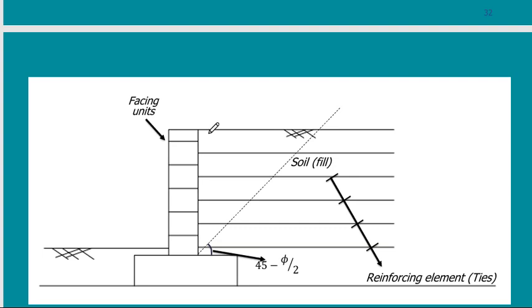I will find that all of this portion will fall down like this. So actually, when I put my wall, I am preventing this portion from falling. How to prevent it? I need to add, after this line, these lines that are preventing my soil from falling. So I need to add more length to the facing.